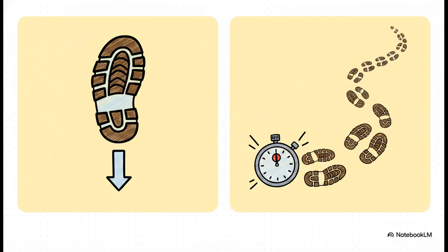If you picture a runner, feed is the length of one single step, while feed rate is how many total meters they cover in 60 seconds. You absolutely need to know which one you're working with when you're setting up a machine.